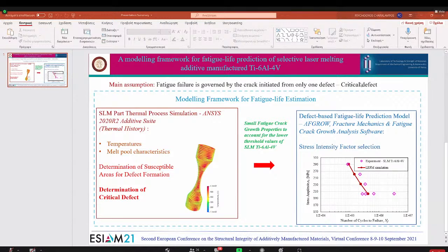It's a fatigue specimen on which a uniaxial loading is applied. So on the thinnest cross-section, the maximum stress will be developed, so the defects on the thinnest cross-section were considered as the critical. I hope I answered your question.